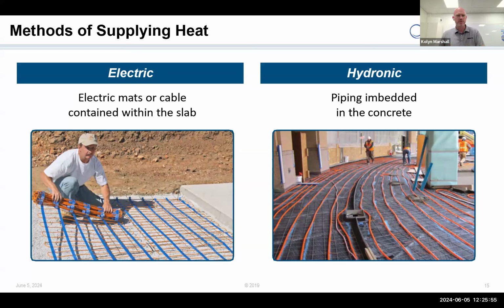You have so many watts per square foot, 35 to 50 watts per square foot to melt snow. And that equates into so many amps at a voltage. And as long as we have the power supply, we can do as large of an area as we want. I have done parking lots, 10,000 square feet of parking area at a location because it was a casino.